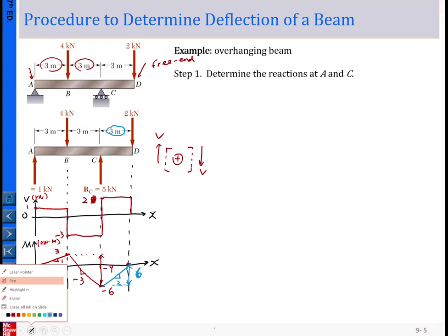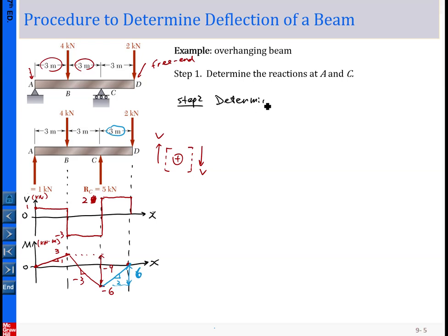So with this information, then plug in our previous example here. So step 2 is to determine m of x, just like showing here. Okay, so now step 3, plug in our equations: 1 over rho equals m function of x over EI.